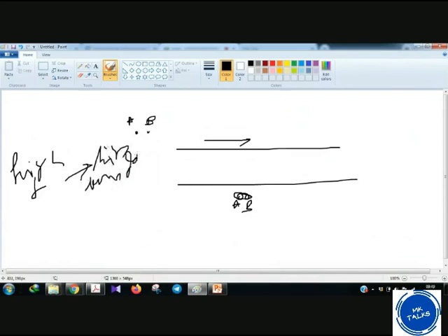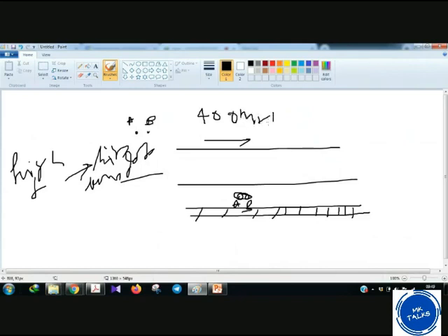Generally, high frequency GPR has high resolution and low depth of penetration. Okay, now let me give you another real example, laminar beds. You know laminar beds, laminations in sand. If you are using a high resolution system like a 400 megahertz system, you can delineate these laminar beds easily, because they are very thin beds.